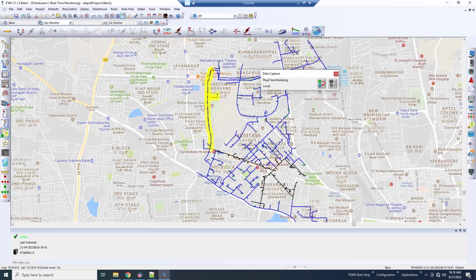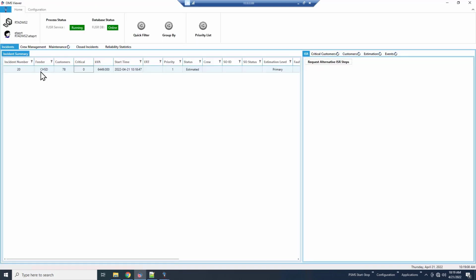time goes on. So now I'm going to inject this fault indicator seeing the fault, but these fault indicators up here don't see the fault. So now what we should see is this section here should be the prediction zone. So as we can see here, we are predicting that the fault is somewhere here. We still have de-energized the entire network, but we're predicting that the fault is somewhere in here based on the fault indicators.